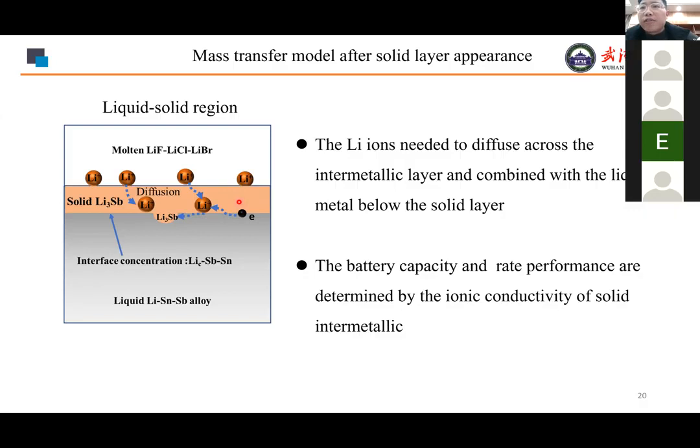The ionic conductivity of lithium antimonide and lithium bismuthide were measured by Hutchins and Wapner. The two intermetallics have a high ionic conductivity, so the lithium-tin antimony and the lithium bismuth batteries have high capacity. All of the bismuth or antimony in the positive electrode can be converted to lithium bismuthide or lithium antimonide.